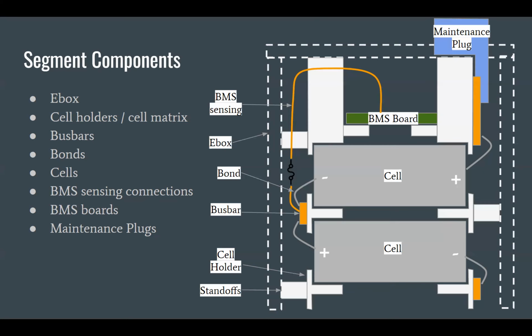And so that means we have to prove through FEA that we can take a 20 G load upwards. You basically imagine I took the pack, flipped it upside down, and dropped it. I obviously don't want this PCB, this little piece of fiberglass, to take all of that force and load. So instead, we make the cell holder stick out, so that it can take those forces and loads.